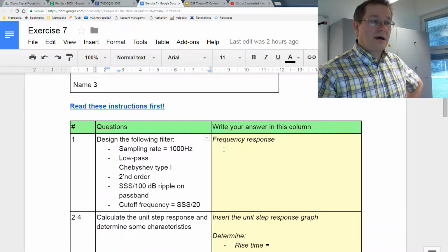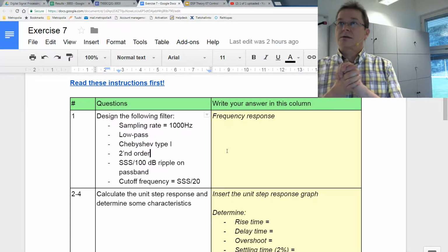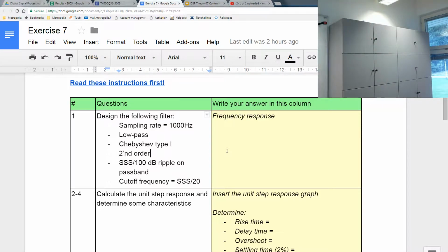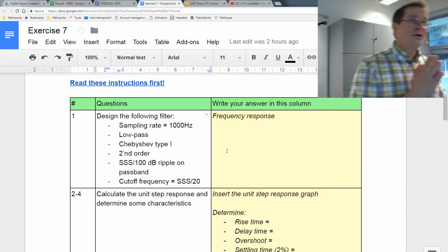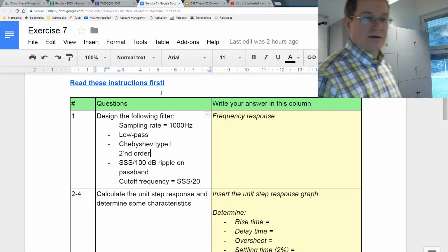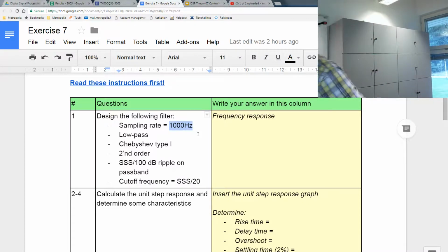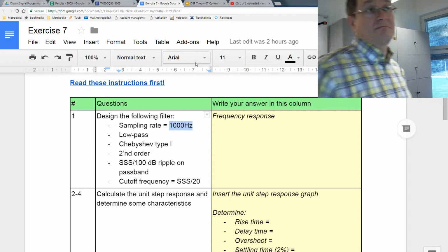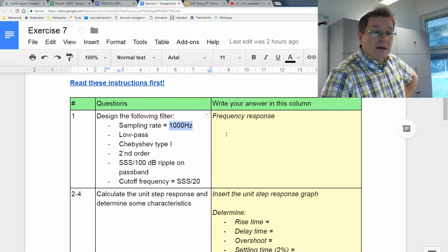So okay, the first one, almost 3 credits. It's just that you can call a correct filter design program or use the FDA tool to design that filter. And as you can see, we are not talking about audio systems anymore, so its sampling rate is 1000 samples per second, meaning most probably a system controller, that kind of thing.